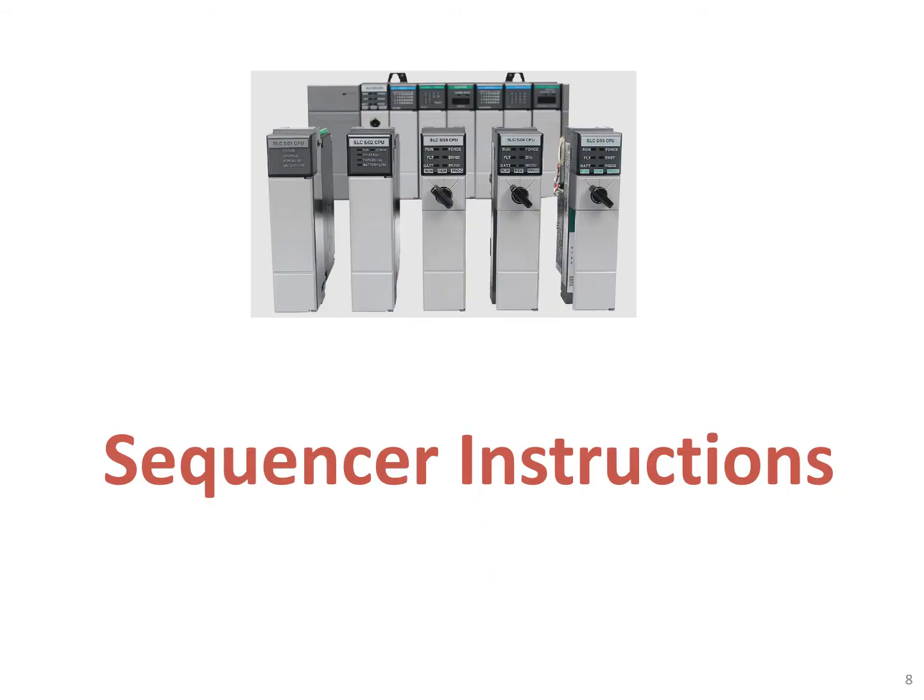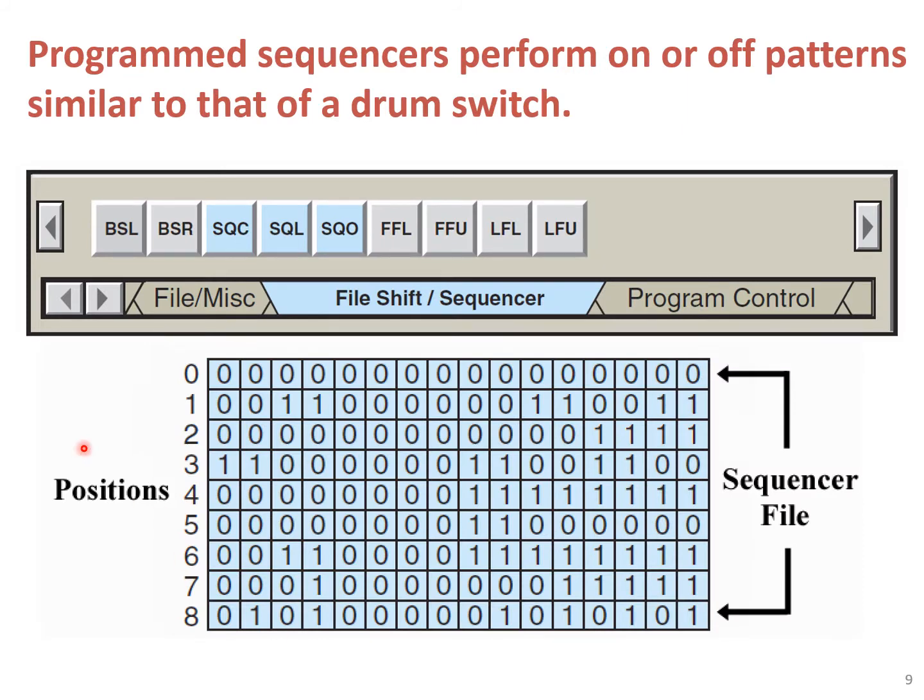Sequencer instructions. Program sequencers perform on or off patterns similar to that of a drum switch. So here for Allen Bradley PLCs, for RSLogix, basically we have sequencer instructions SQC, SQL, and SQO. We'll discuss these specific instructions one by one.